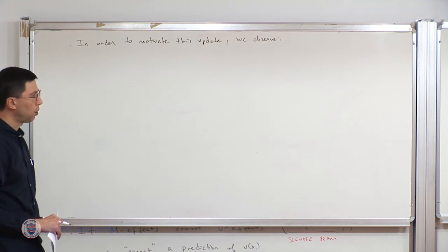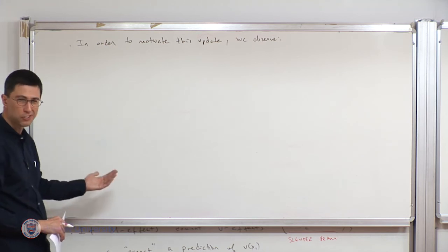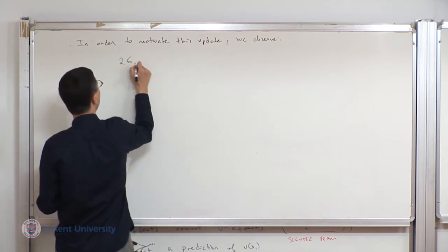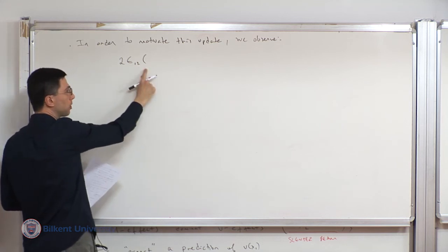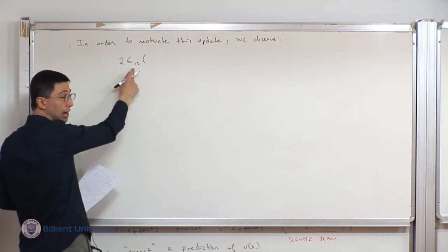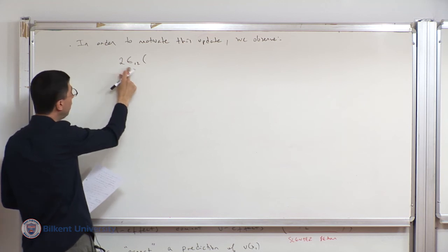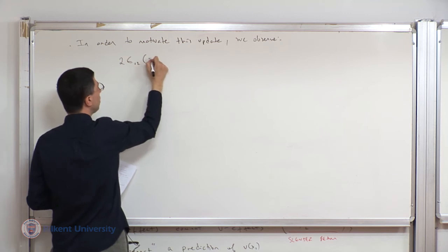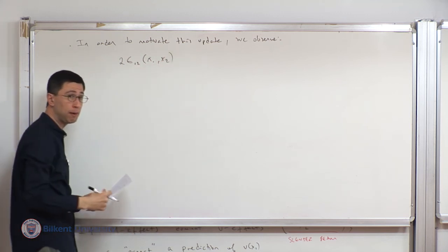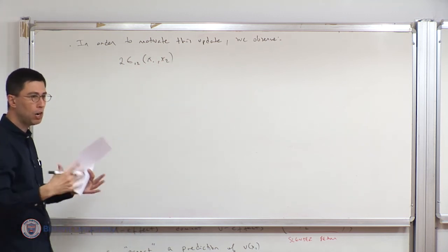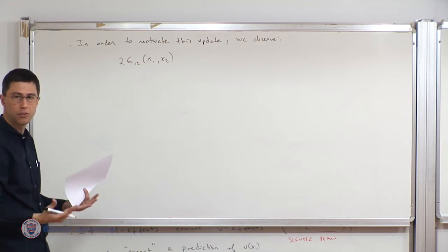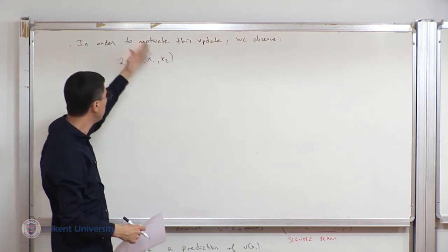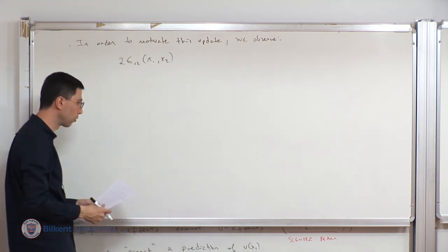All right. So knowledge of elasticity theory eventually will guide us through, and it's going to do that in a very simple manner. First, I'm going to write the shear stress at any point along the beam. I'm going to multiply it by 2 just for convenience. So the shear stress at any point along the beam, and I'm talking about, at this stage, any arbitrary loading, and I'm talking about the exact result. So it's a function of x1 and x2. It's not necessarily a constant along any coordinate. It can change all over the place.